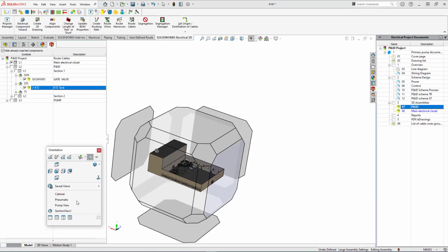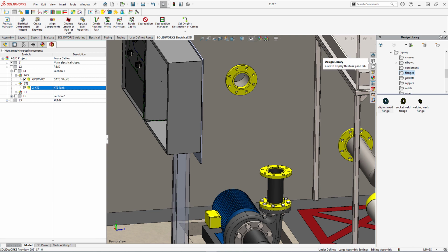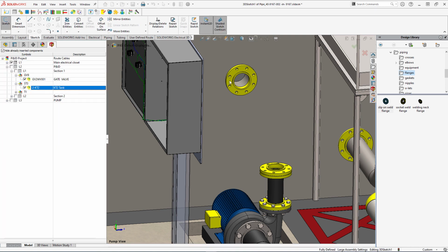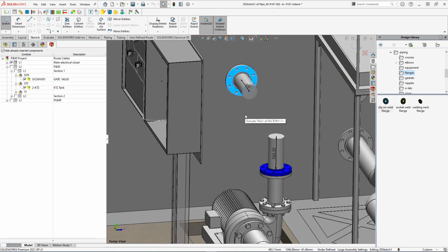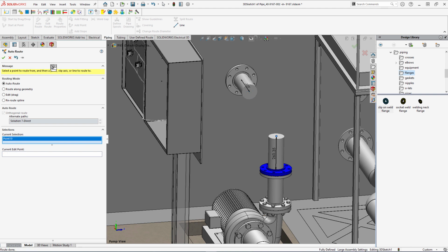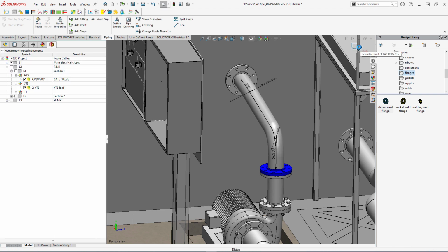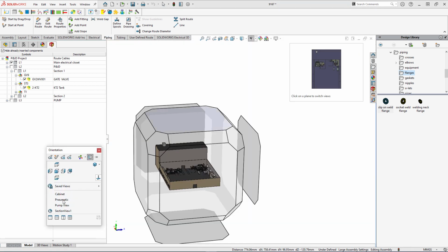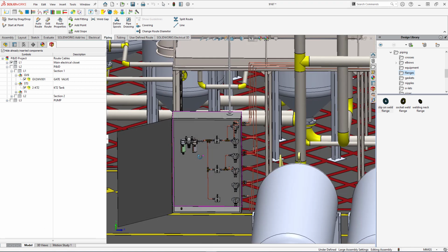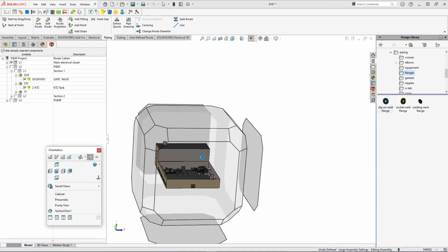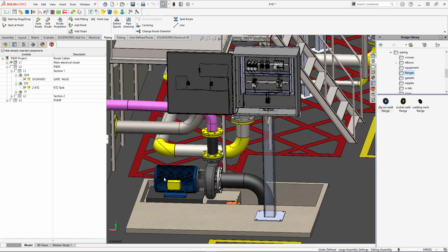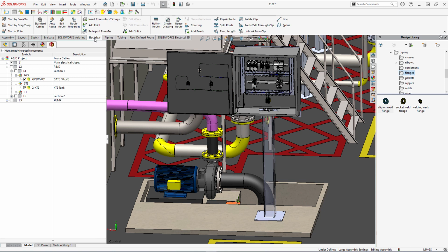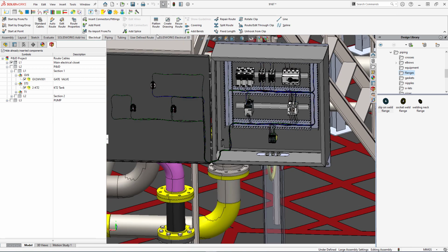To route a pipe, just insert a part from the piping or tubing library and drop it on the assembly. The route is just a 3D sketch that can be drawn manually or using the tool AutoRoute. On the same project, I can insert my pneumatic components if I have them, but also I can insert my electrical components. SOLIDWORKS can route wires, cables, and harnesses for me.